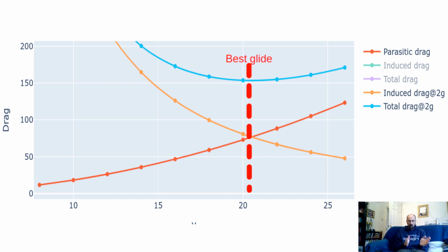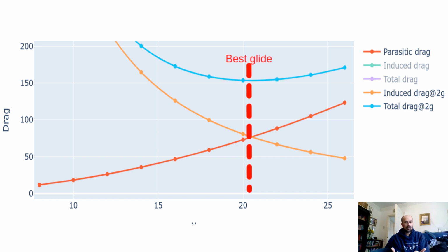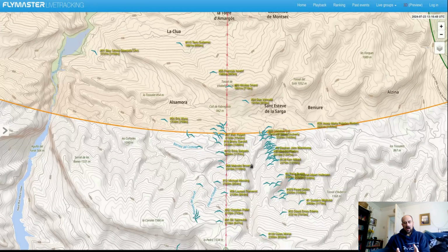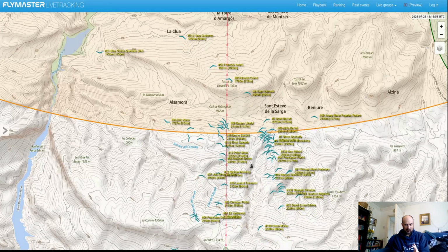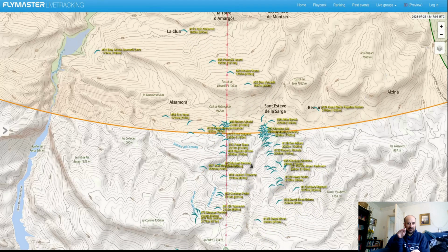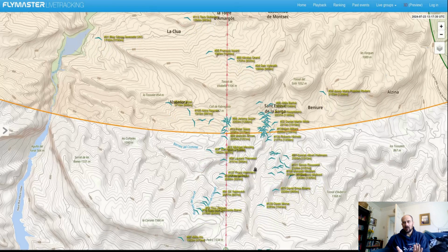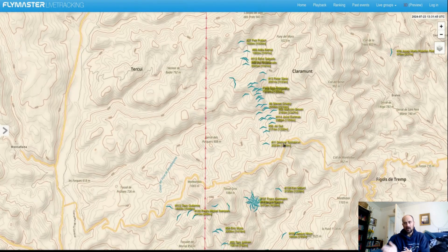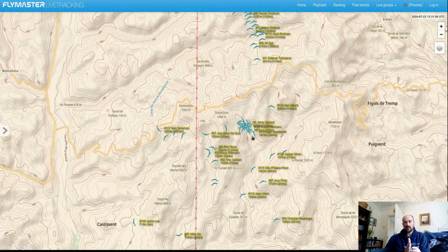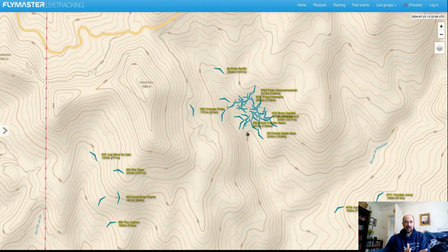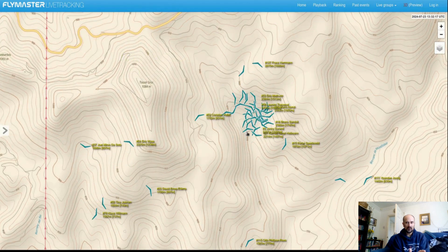So that means that all the time you're thermaling, it's very definitely induced drag that's the more important term. In fact, for a lot of the flight, when you're thermaling, soaring, searching for lift, trying to eke out a sort of lifty line and make the most of it, all that time that you're not flying faster than the best glide speed, then the induced drag is the more important term.